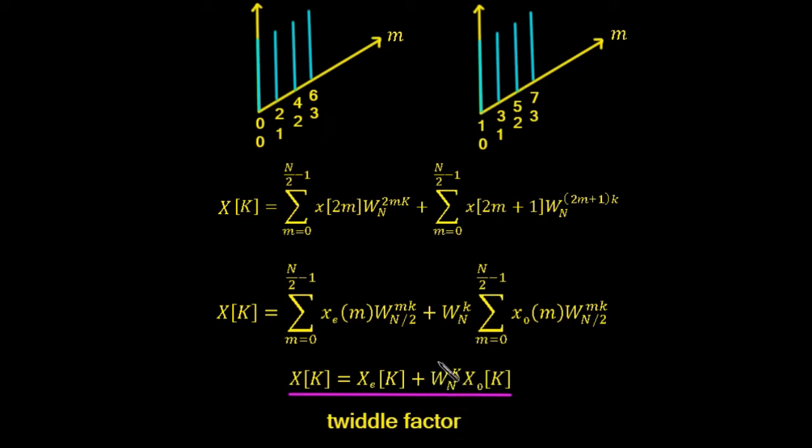So if you like, what this W to the k sub n does is it slides these values here one position to the left, because if you noted that whenever we generated the 0, 2, 4 and 6, those were sitting with the 0 point initially sitting here, but the 1, 3, 5 and 7, the first point was actually sitting here.